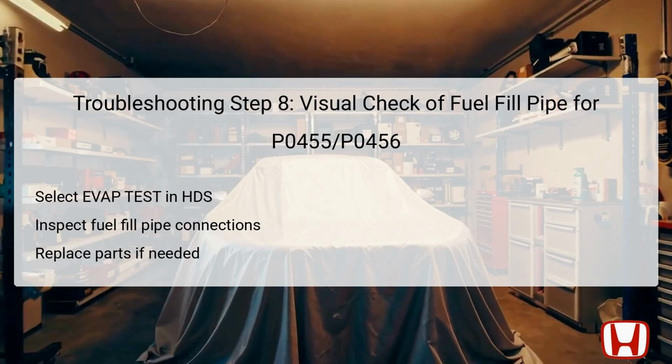Carefully examine all the connections for signs of wear, corrosion, or damage. If any inconsistencies are found, the corresponding parts must be replaced to prevent leaks from occurring within the system. This ensures that fuel vapors can be properly vented back to the fuel tank and condensed for recirculation. Maintaining the integrity of these components is essential for proper fuel system operation and optimal vehicle performance.